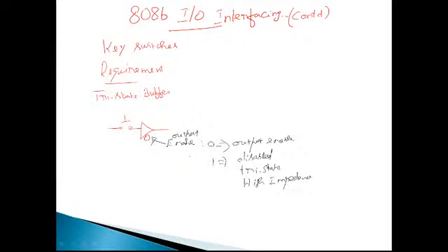So how do I do that particular thing? When the switch is closed, I should get a 0. When the switch is in the open state like this, when there is no connection, I should get a logic 1. How do I do that? Just this arrangement will not do now, because the other end of the wire is nowhere connected. As we have discussed in the last class, I'll just recall, right?